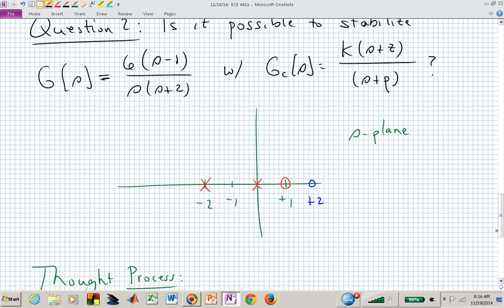Now, can we just put a 0 down by itself? No, we can't just add zeros. It'd sure be nice if we could just get out our zero shaker and sprinkle zeros all over, but then we would have these derivative actions. And remember what a derivative Bode plot looks like. That just keeps going up and up as we get higher and higher frequencies. And so if we have any noise, that noise is amplified a lot by these derivative actions.